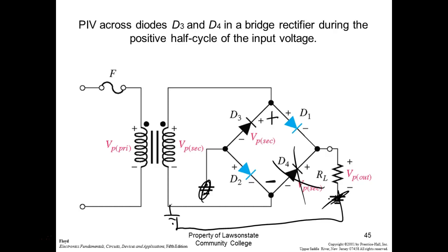So these are bridge rectifiers. And you can get them in different sizes depending on the amount of current, so that's a bridge rectifier right there. And this is a bridge rectifier right here. So here's AC, here's plus DC, and here's minus DC. I forgot what this guy right here is rated at, but this would have a pretty good sized diode, and it actually can be decent. So you can get these in all different sizes depending on how much current you want to put through it, right? And you still run into these discrete components.